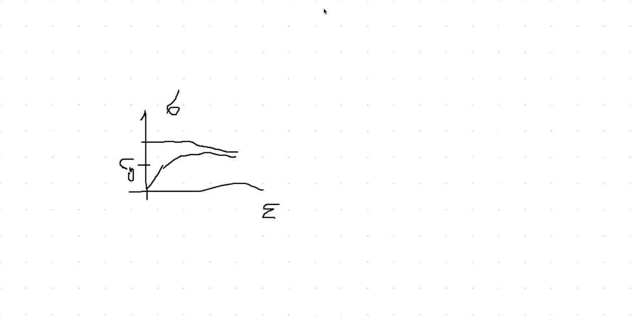If you have a saturation hardening, now this is your sigma epsilon. So you have linear behavior until the limit of elasticity, and after that you have this kind of nonlinear behavior that goes into sigma infinity. So this thing here is a convex, maybe not perfect pitch, sorry about that. And then when I'm computing this one here, this is my gamma n plus 1. And this is my phi n plus 1.